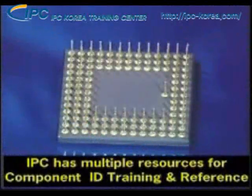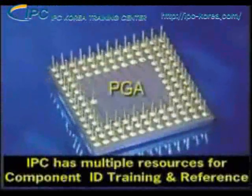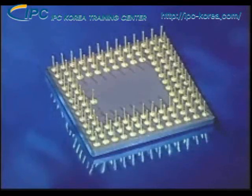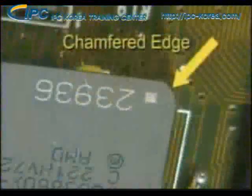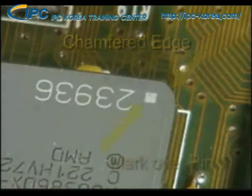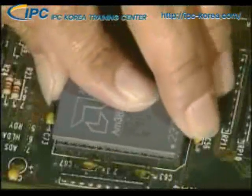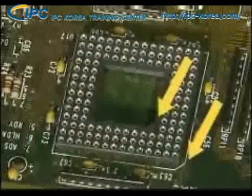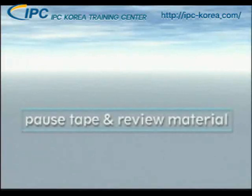Our last through-hole IC is the most complex. Pin grid arrays have several rows of leads extending from the bottom of the IC. The rows make up a grid of connection points. PGAs come in plastic or ceramic packages. For orientation, there is usually a notch or mark directly over pin 1. PGAs are often installed into sockets that have been soldered onto the circuit board. The pin 1 location on the socket will also be marked in the same way as the PGA for proper alignment. Let's stop again and review the material we just covered.